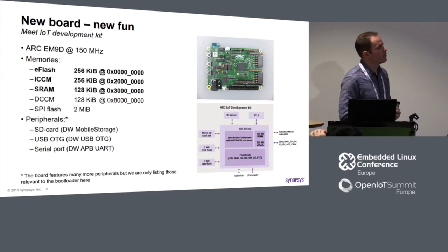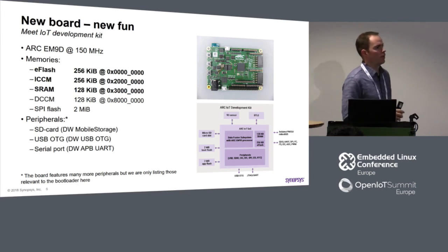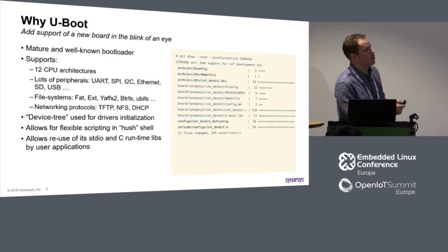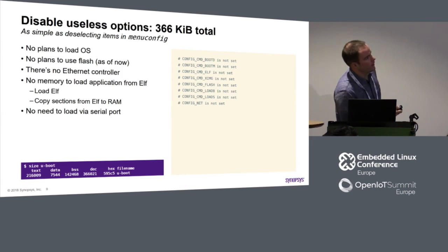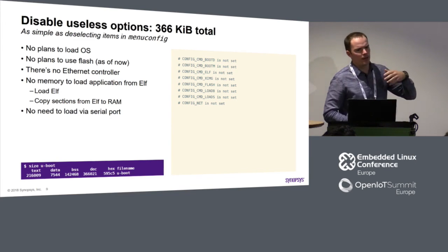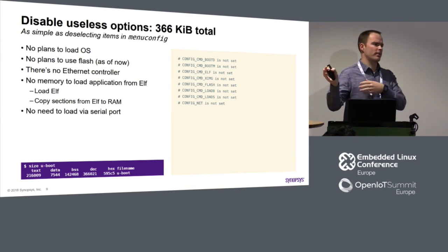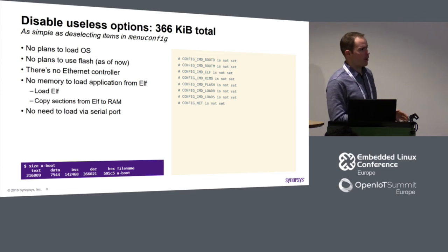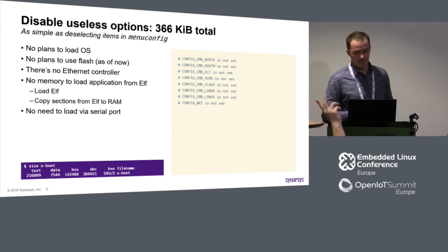So this option doesn't prevent U-Boot from running bare executables, right? No, that is a very specific option which does quite a lot of things in preparation for starting the Linux kernel. Yeah, and then loading stuff, changing things like device tree blob addresses, and then doing a lot of checks, preparing registers, caches, and then passing control. The go command is very simple. It is implemented as a jump. Okay. Thank you.